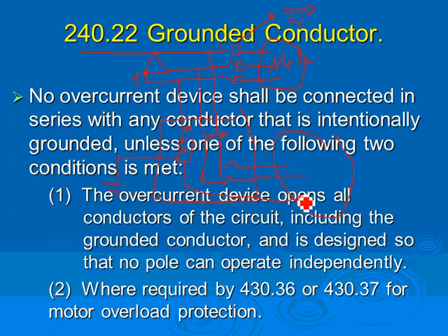You send an apprentice there, they look at this white conductor bar, so they grab this thinking they have a neutral. This is very similar to single phase, right? They grab this thinking it's neutral, take another phase from here, not knowing that they're pulling 240 to all these receptacles instead of 120. So anything you plug in, what's going to happen? You will put 240 across 120 devices. Right. In Milwaukee, an inspector told me that a guy burned multiple lights multiple times before he realized that the voltage was not 120, it was 240. He thought there was something wrong with the lights.